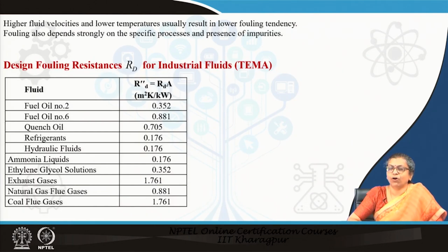And it is also important, suppose you have to clean the tubes very frequently, that is not at all a desirable situation. Normally, tubes are cleaned either by mechanical means or by chemical means. So we would always like to schedule the cleaning of the tubes with the original shutdown of the heat exchangers. So you need to remember two things. When you are taking fouling factors into account, you are providing some additional area to the heat exchanger.